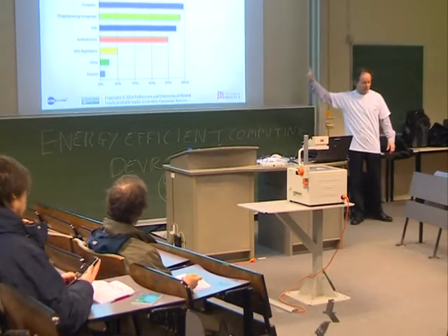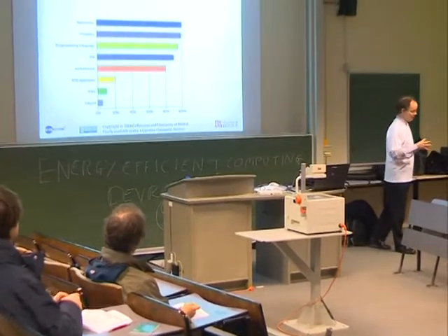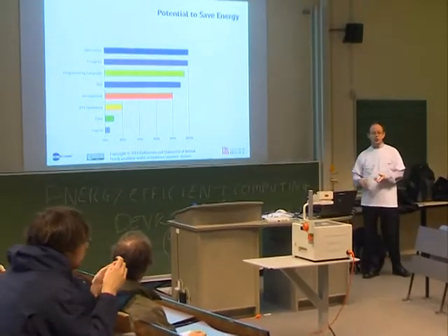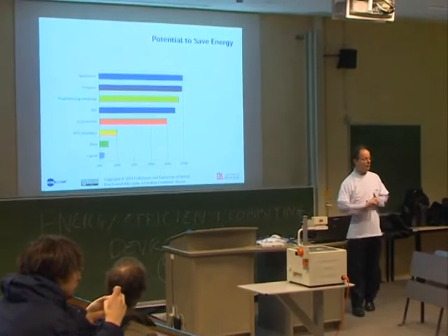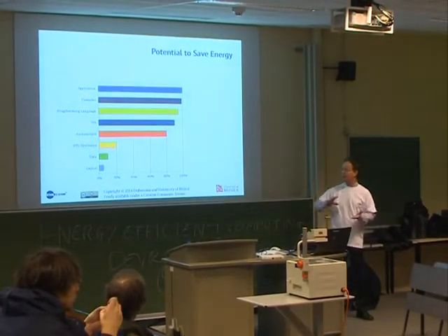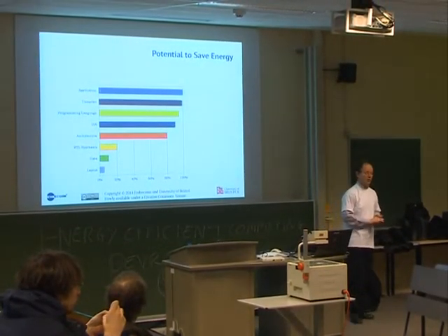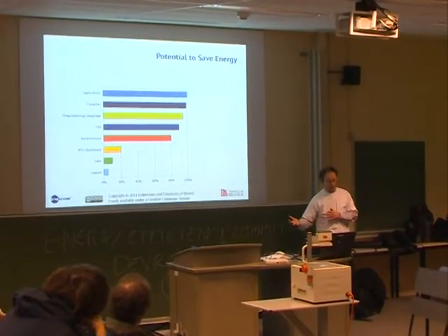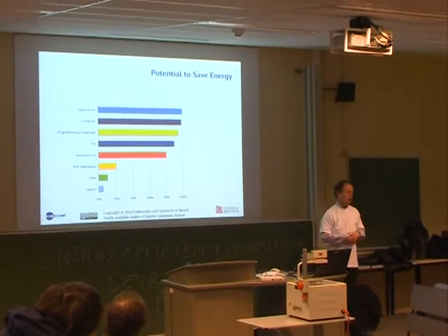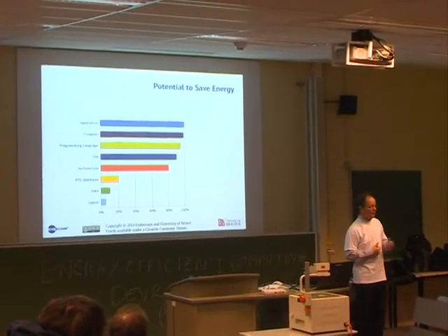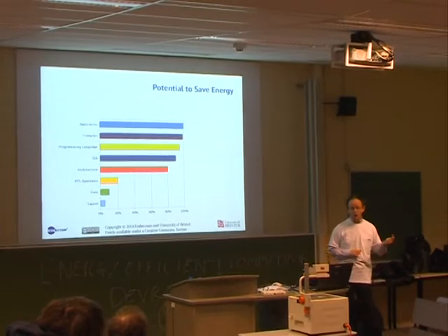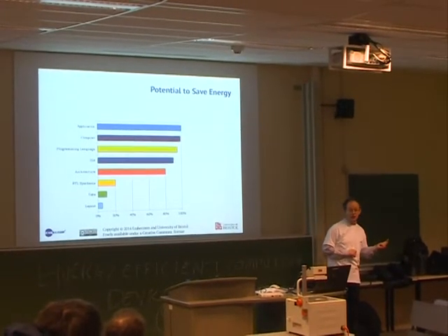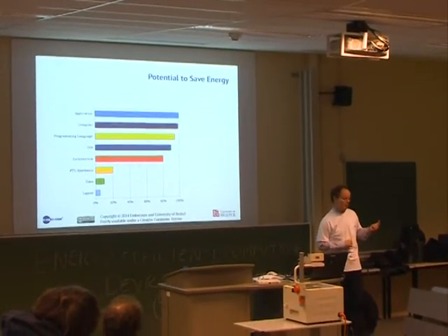These bottom 4 bars, hardware guys are brilliant. They can change the voltage, they can change the frequency, they can clock gate every circuit, they can give you sleep modes. And I quoted the example yesterday of one of the little 8-bit AVR chips, which, if you run it on its standard configuration with a 2 megahertz clock at 3 volts, in standby, it'll take about 290 microamps.